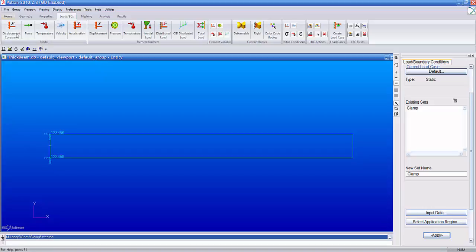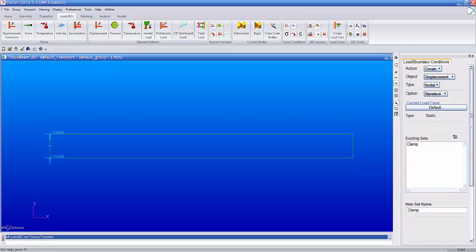For the load, we want to define a shear load at the right edge of the beam. Now when you look at the derivation given in the reference video of the problem description, when you define a Timoshenko beam, you define the shear as a shear load applied to the surface of the tip of the beam.